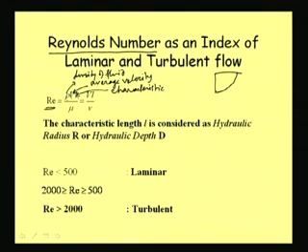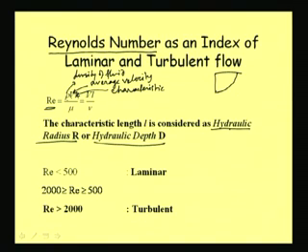And in open channel flow, we take this length term as either hydraulic radius R or hydraulic depth D. In the last class itself we discussed what is hydraulic radius and what is hydraulic depth. So it is basically a characteristic length that can be different. In fact, for another problem or another study, what we call a boundary layer, that length becomes different. So this length can vary from case to case, or depending on the problem we take a different characteristic length.